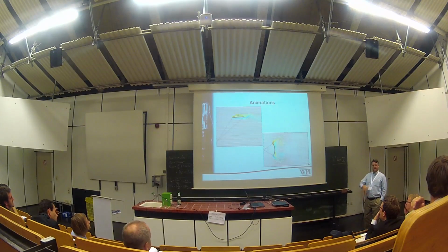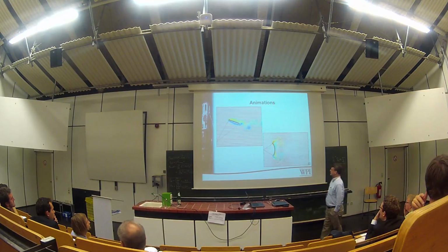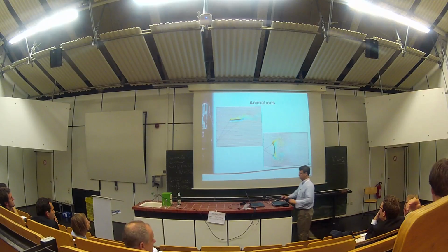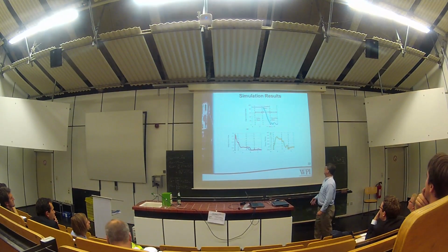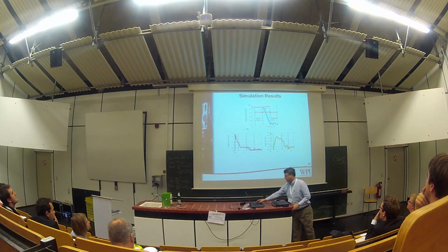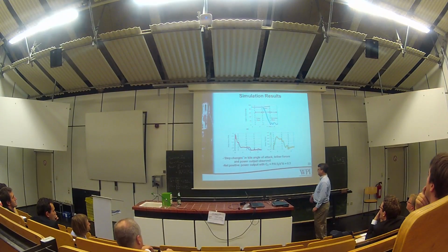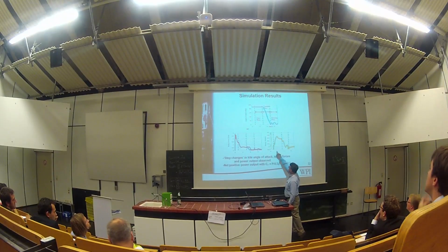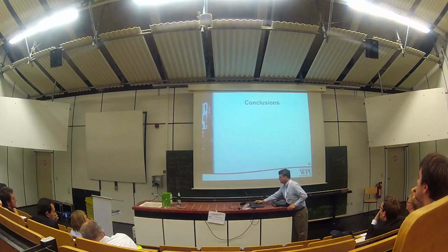Our goal is to improve on linear quasi-static aerodynamic models, if there's more we can learn from the CFD work, and of course there are plenty of CFD challenges along the way. From the CFD simulation results, we see these step changes in the angle of attack and in the tether force, in the red here, and we have shown net power output with this CFD code, positive output during a power phase compared to a return phase, for example. But in 2D for right now.